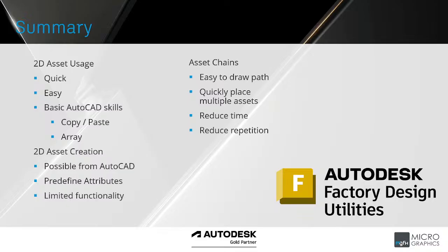So you'll find that you'll probably follow the process that I covered in one of my previous webinars, where you would publish from the 3D side and generate the 2D blocks. But if you are just stuck to the 2D side of things, you don't want to work too much with Inventor, it is still possible to publish assets from the 2D side, even if you need to use just a very little bit of Inventor. But we are able to publish 2D assets.